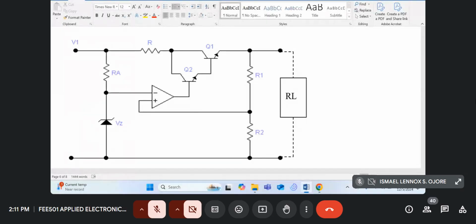So we're considering the series regulator, the series DC regulator. And this is the most common configuration. We have your unregulated input, V1. We have your reference element that gives us a value Vz, where Vz is the rating of that particular zener.